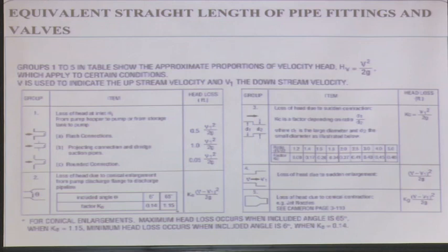So, you can see here there are different other areas, expanders, reducers, all are in terms of V square by 2G, some coefficients are there. So, you have to also calculate the heads for that, okay. Every case is there. So, like this each and every item has to be scrutinized, has to be isolated, and against that the equivalent head, equivalent length has to be calculated, then it has to be summed up.